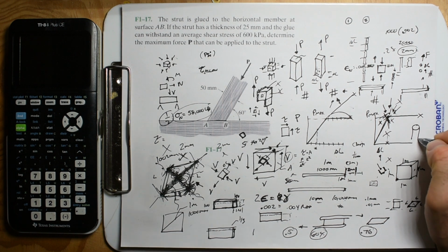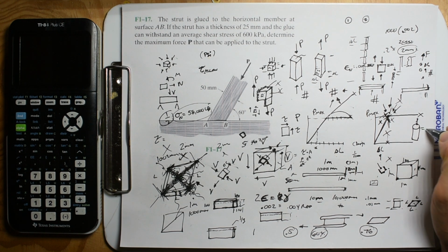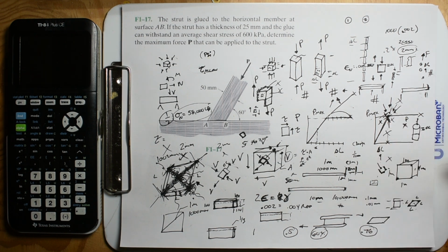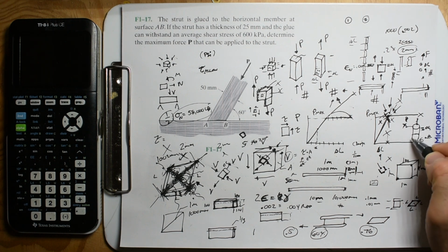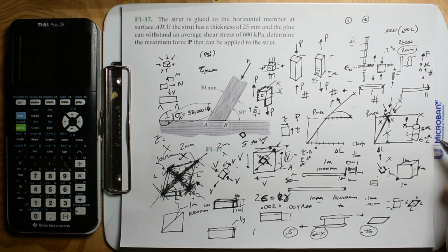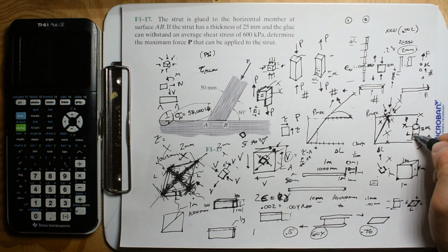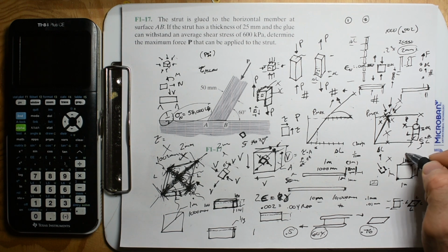You take a specimen of concrete, you pull on it, you measure the force it took to break it, and you measure that change in length. That's basically what you're doing: load and change in length. Then you call this strain, which is the change in length compared to the length of the specimen you were using, and now we have a parameter that's useful for every length of concrete.